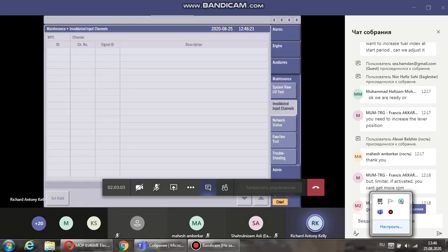But wouldn't a fuel pump feedback be almost as important also? It is important, but of course you can invalidate the input there. Okay. With your feedback sensor from your fuel booster, depending on the software age, you can invalidate or you would just disconnect the cable to your feedback sensor.